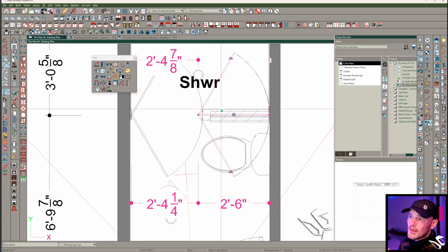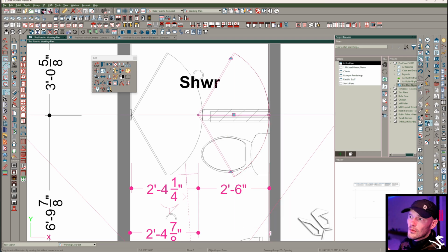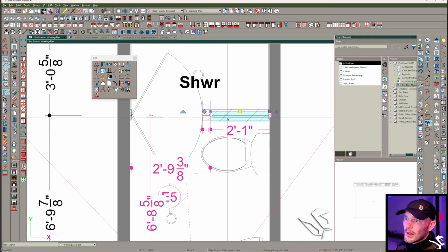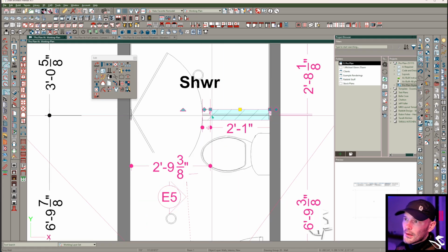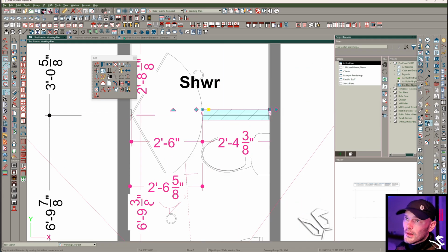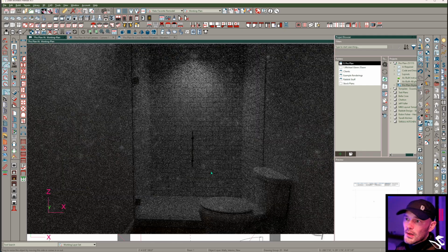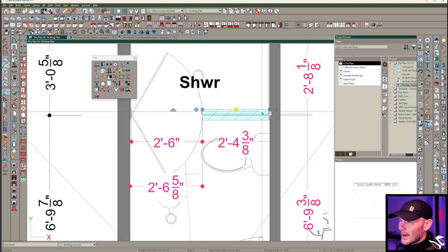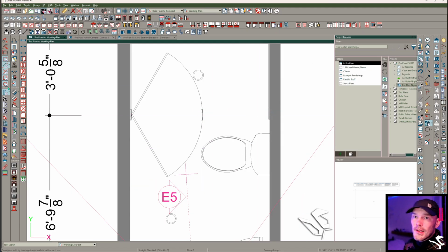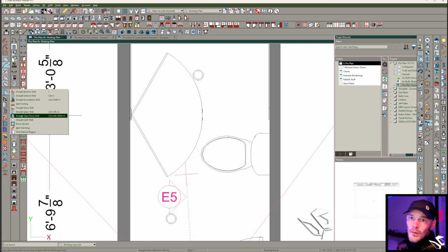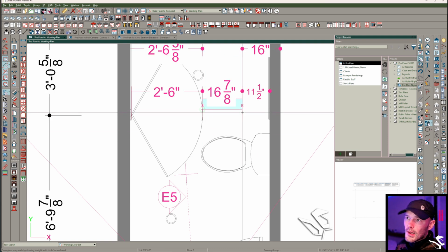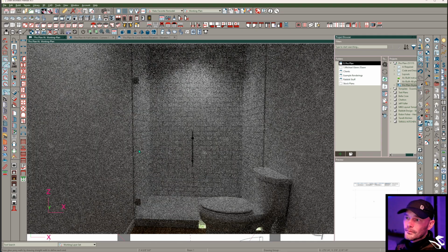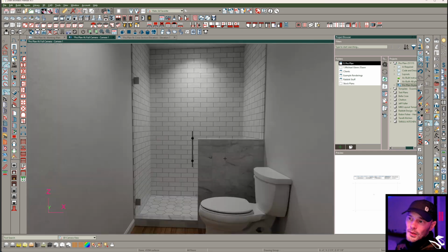And so when I draw this out, it doesn't just overwrite that existing wall. What do I have to do? Well, I kind of have to get this door out of the way. Let me get that out of the way. For some reason, this wall is not perfectly overwriting that other wall. Let me snap this. Let's look at 3D. What has that done? Well, it hasn't done anything good in this case. I almost have to just delete that section and start from new. And what I'm going to do is start with that straight glass pony wall. And here's what it's going to look like. There we go. I've got a half wall in place.